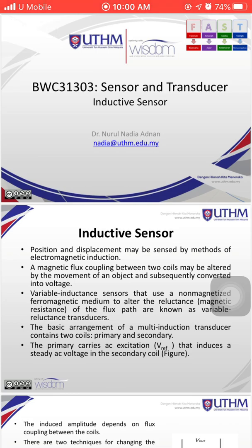Okay, so how does it measure the object? An inductor develops a magnetic field when current flows through it. Alternatively, current will flow through a circuit containing an inductor when the magnetic field through it changes. This effect can be used for us to detect metallic objects that interact with a magnetic field. Non-metallic substances such as liquids or some kind of dirt do not interact with the magnetic field. So an inductive sensor can be operated in either wet or dirty conditions.